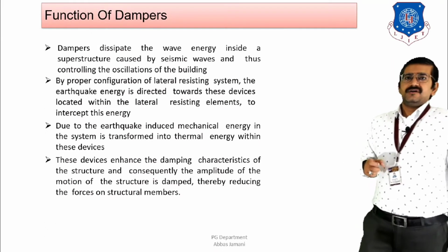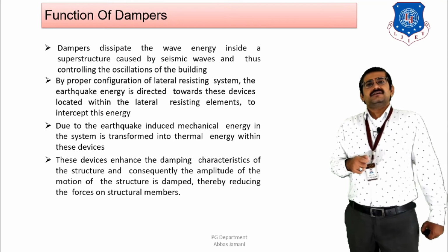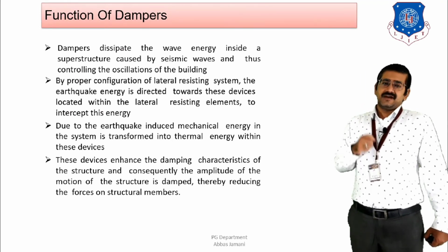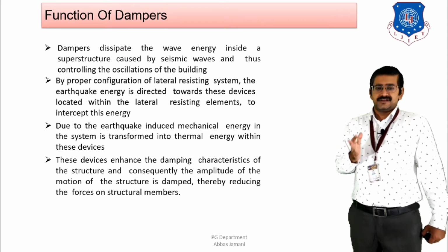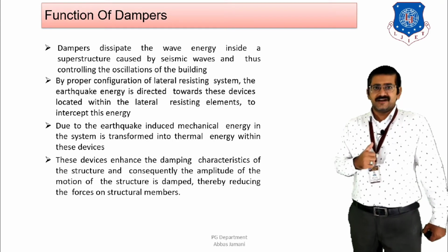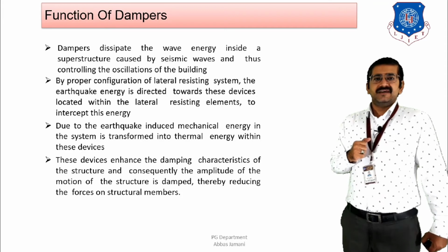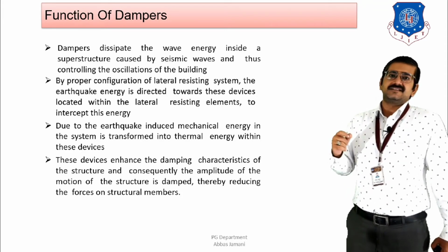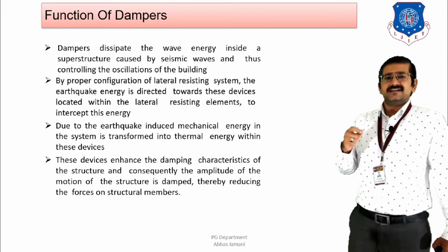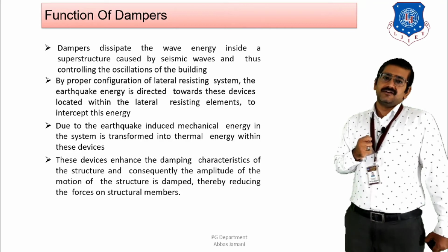Right? Now that brings us to the question of what is the actual function of a damper. I think by now the function must be much clearer to you, but let us look at it once again. That is, the dampers dissipate the wave energy that will be transferred to the building when the seismic energy is acting. Right? And as a result of that, the oscillation of the building will also initiate.